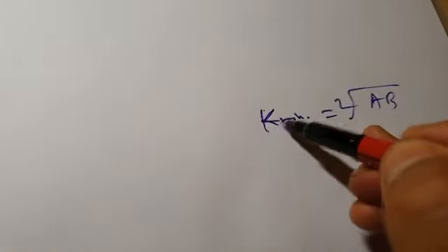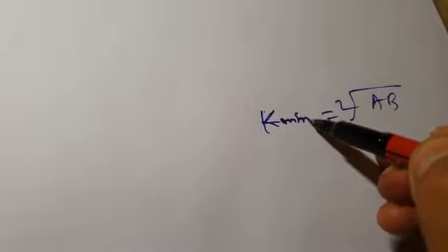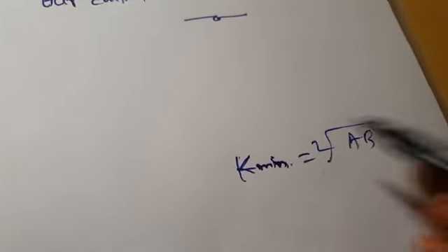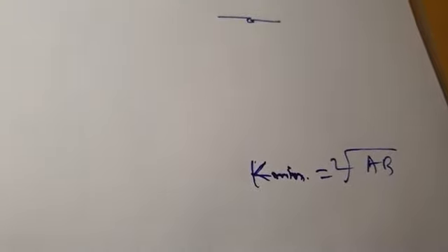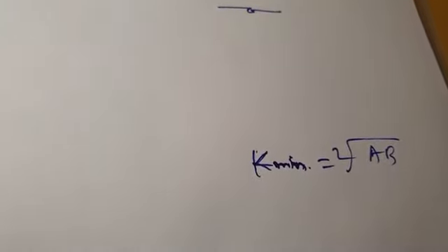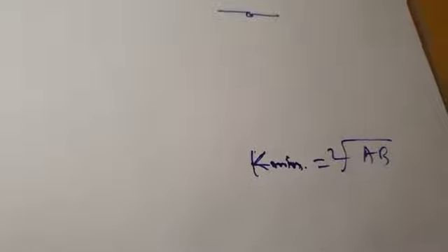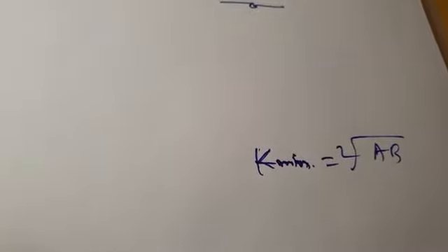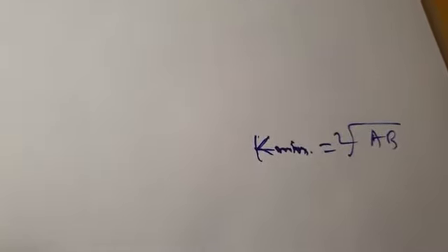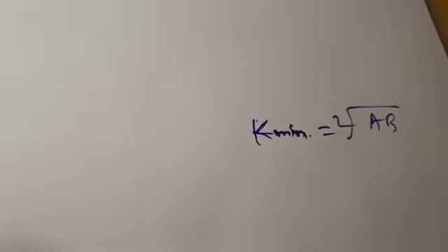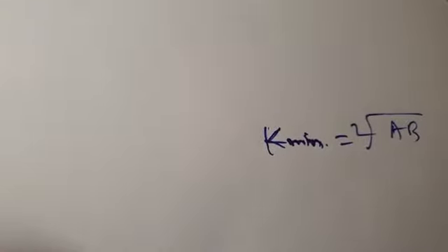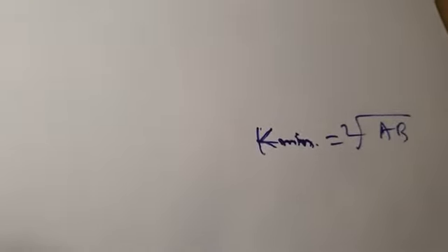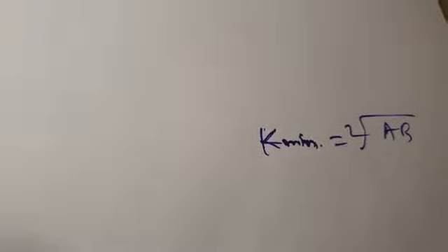We took an example to find the minimum cost of the filter. So whenever you design the tuned filter for suppressing the harmonics, your filter also provides some reactive power compensation, and you should always try to design it for minimum cost. We derived the condition for minimum cost and saw how to find it. Finally, we looked at the effect of network impedance on filtering.